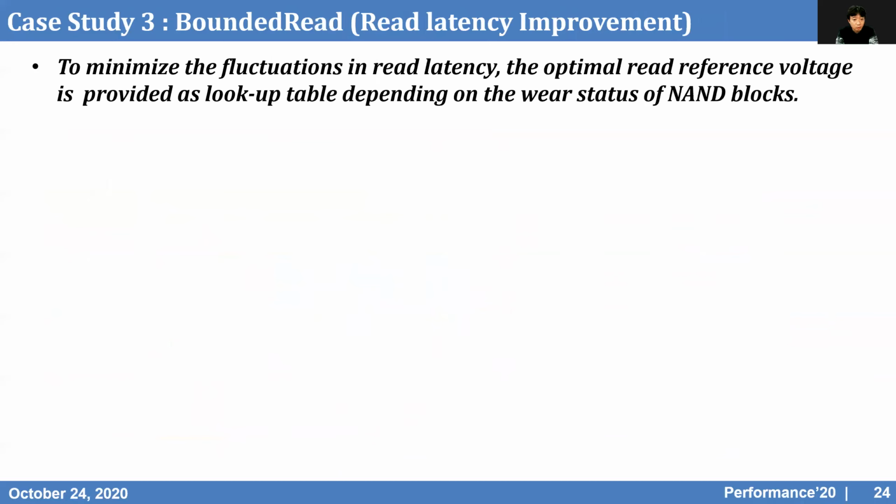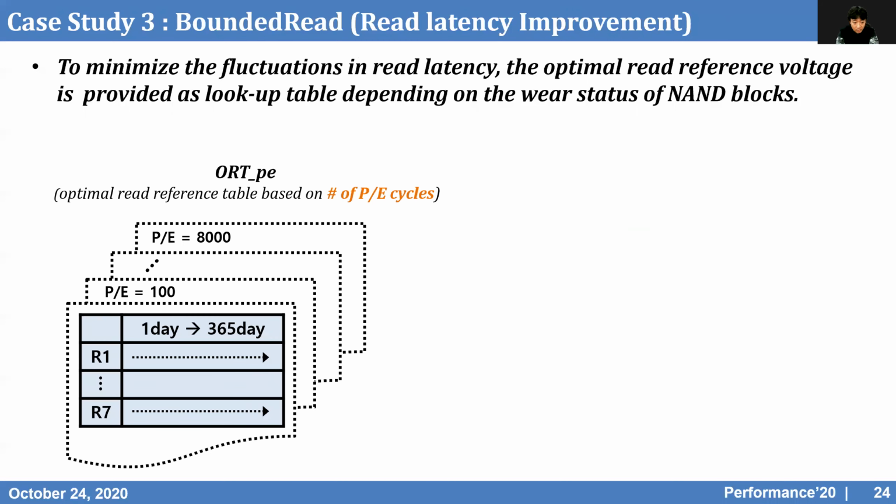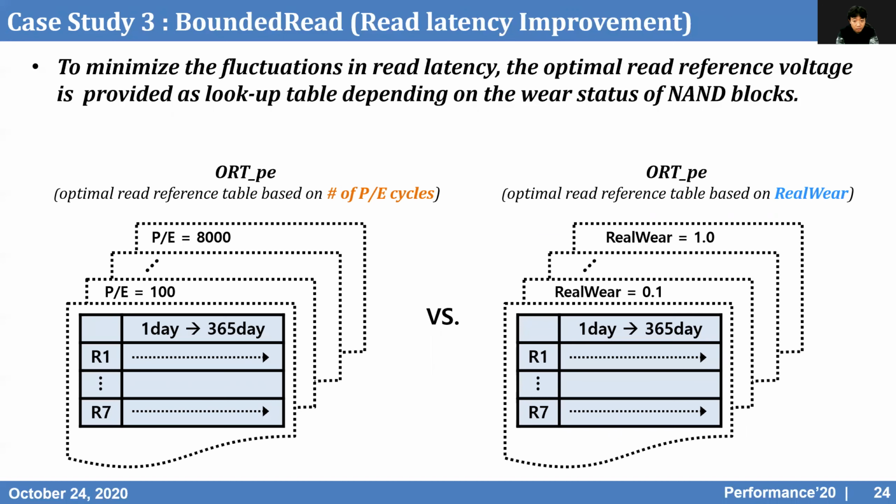Finally, RealWear can open new opportunities to optimize flash-based storage. To minimize the fluctuation in read latency, we try to apply the optimal read reference voltages, which are provided as a predefined lookup table, depending on the wear status of NAND blocks. We created 2 optimal read reference voltage tables, which we call ORT. One is ORT using P cycles, and the other is ORT using RealWear.